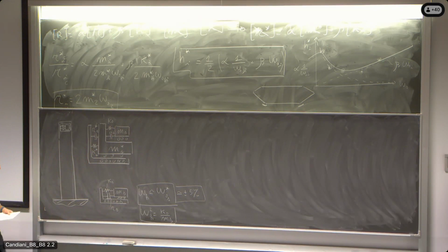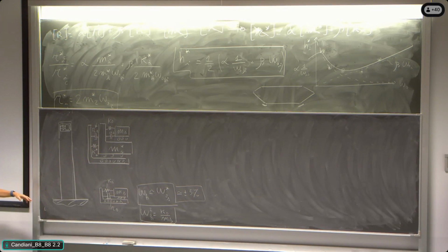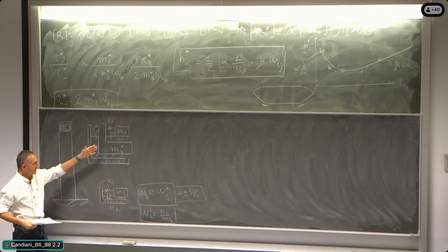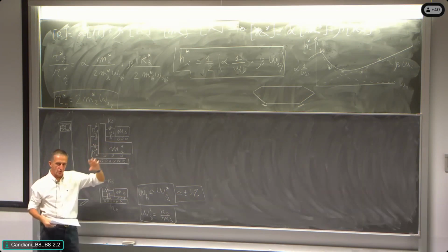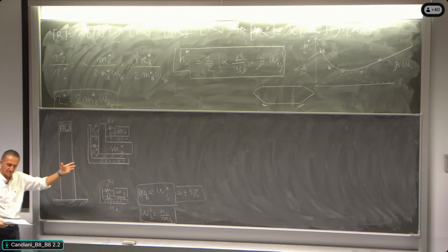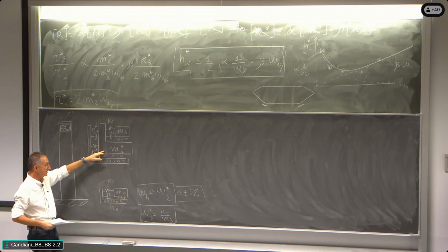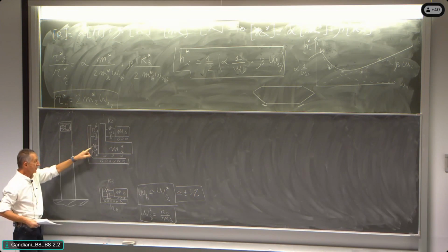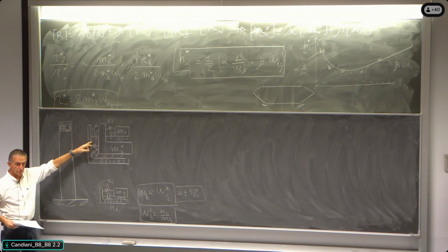All right, this is the drawing. We are modeling the object with the modal representation of the first mode of the structure. And so we are considering the equation where we have the mode 1 that is running, but we are coupling this mode 1. This mode 1 here is represented by the modal mass of mode 1 that is connected to ground through the stiffness, that is the modal stiffness of mode 1, and connected to ground with the damper, that is the modal damping of mode 1.